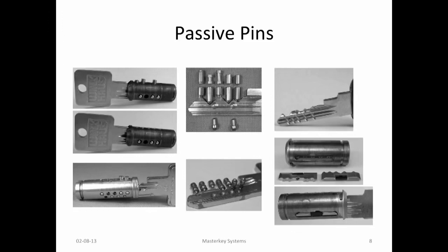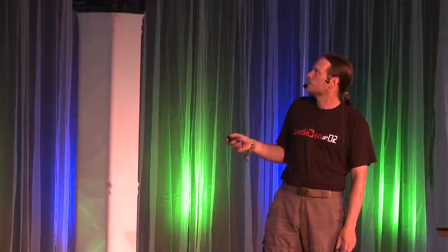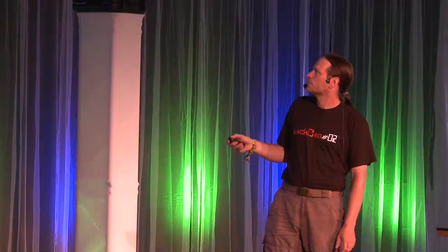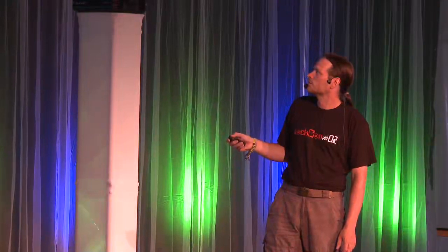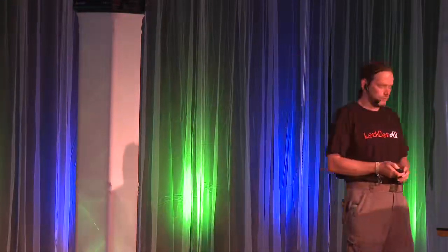You just have keys that have the same key bitting, the same keyway, just with holes in a different position. These holes must be there, so just drill all holes in. Even with something like the right system here, these grooves have their own position where they don't get milled, so that the key cannot turn. But it is always in the same position in the key system.